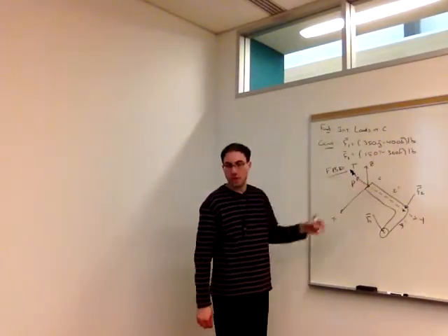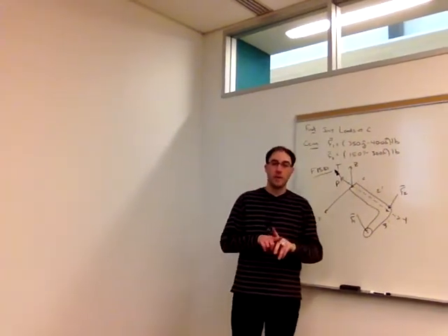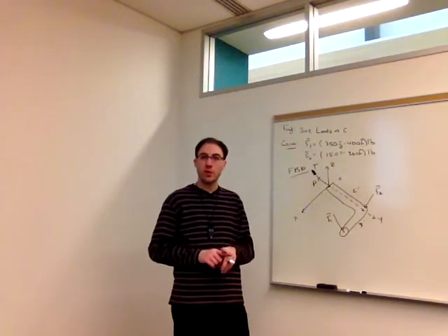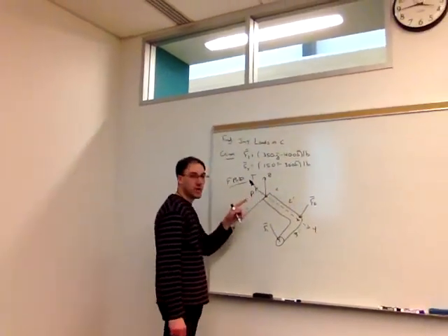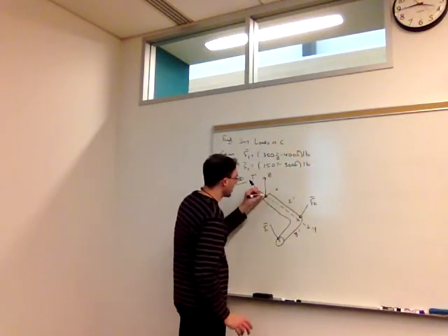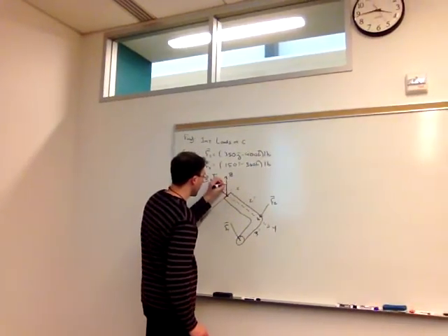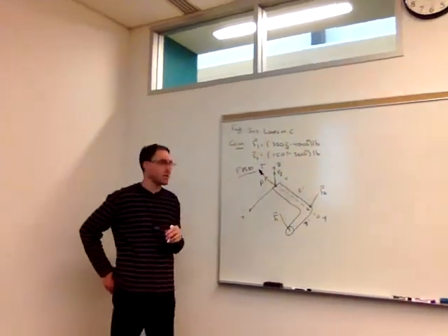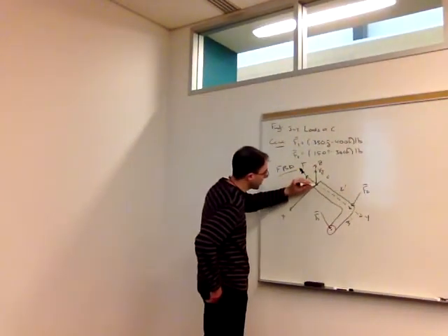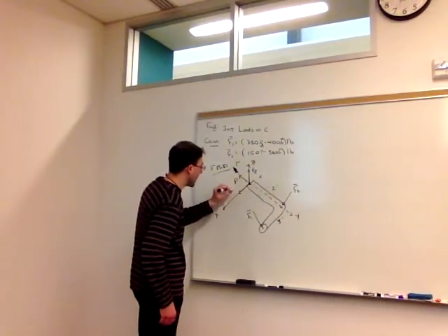Now parallel to the surface of the cut, I'll have two components of shear force, two components of the bending moment. Again, the XZ plane determines that cut surface, so I can draw one component of my shear force, Vz. I'm going to assume it's in the positive Z direction. I'm going to assume that Vx is in the positive X direction.